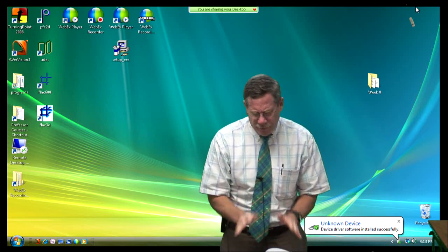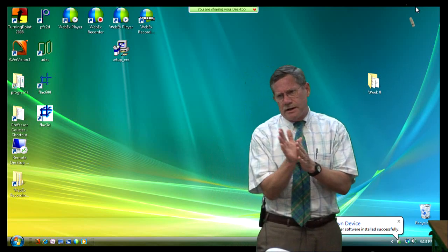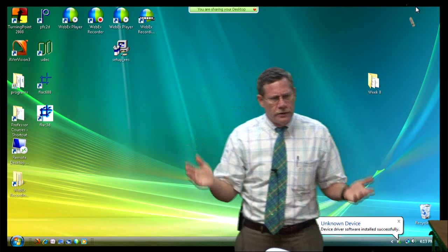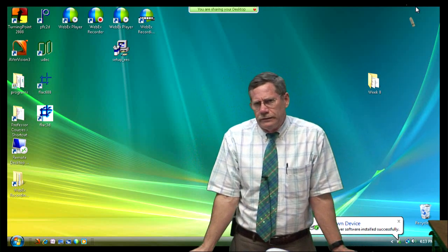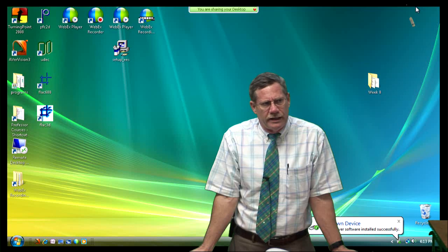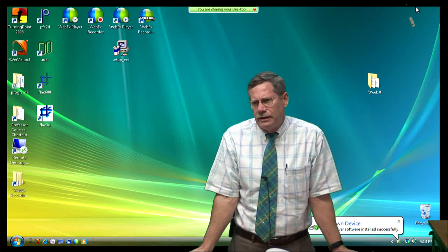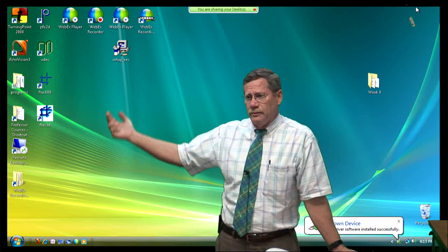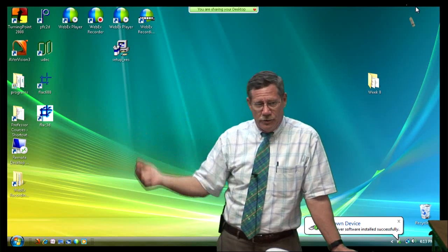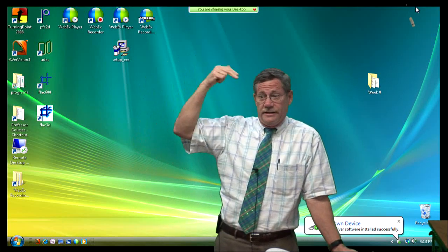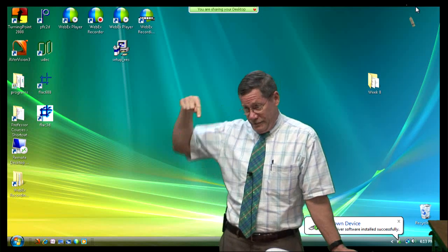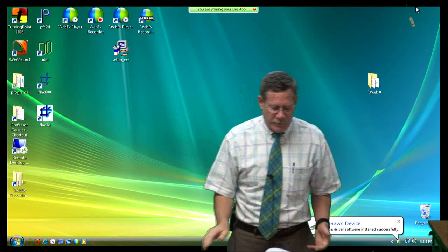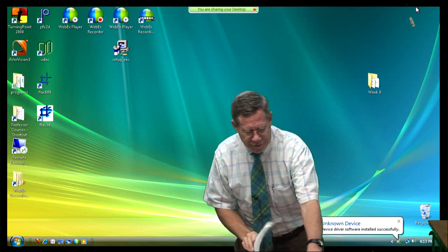Okay, so look at that and realize if something's starting to accelerate, you want to start getting worried. If the movement starts accelerating, that's telling you that rupture is coming. You have a chance to run. It's like being a young Marine and hearing the mortar shell come in. The old Doppler effect. The closer it comes in, the faster you better get down in a hole, or you're not going to live to tell about it.